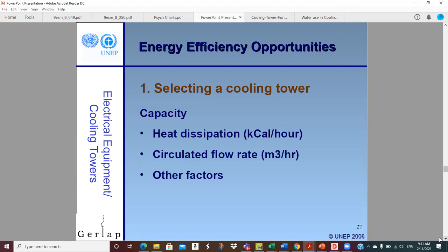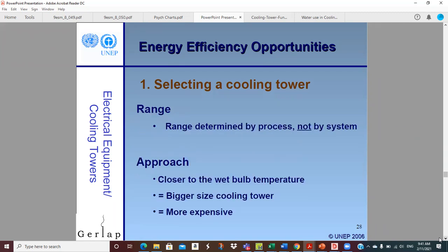If I've got that 1,000 ton chiller with a standard sizing on the condenser, that's going to be 3,000 GPM, and it's probably going to be a 10-degree delta T, at least in the old days, is what they were sized for. Now, you may be doing something different to try to reduce energy a little bit more. But those are key parameters that you'd have to look at.